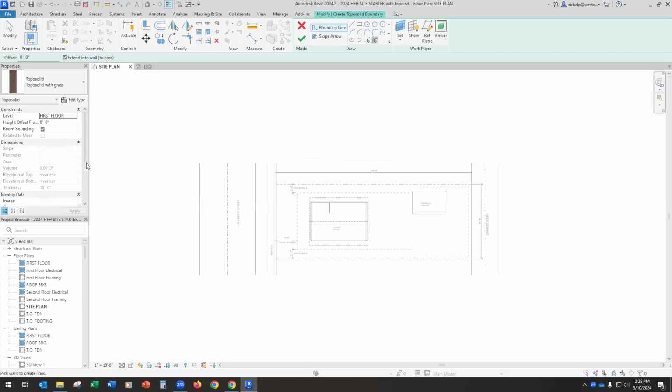Okay. So now, since my floor is at 0, my floor thickness is about 1 foot, and I need to be 8 inches below by code, I'm going to set the whole site at -2 feet down. And then I'm going to gently keep it level around the perimeter of our property and then gently slope it up to where my house is, this little placeholder house.